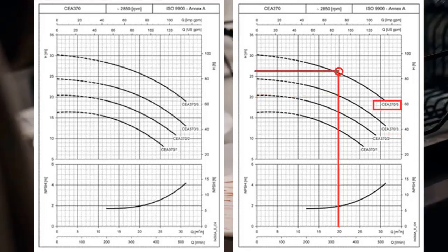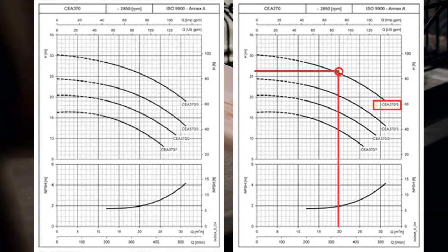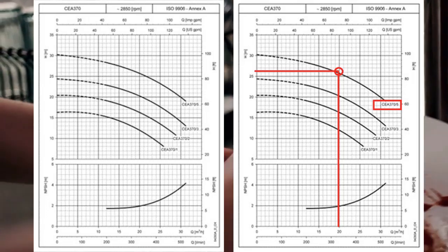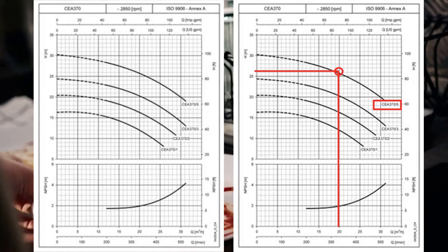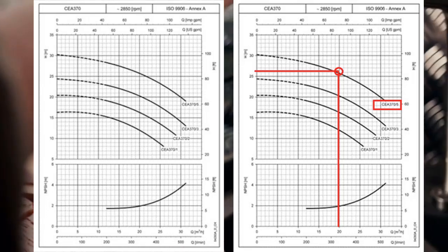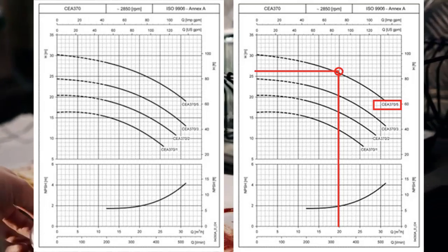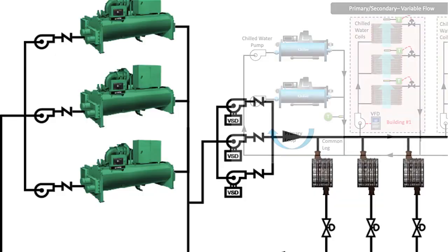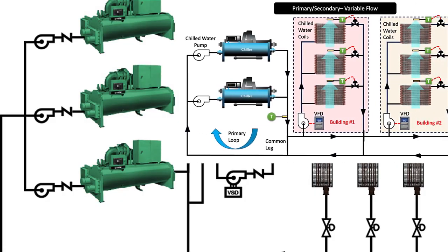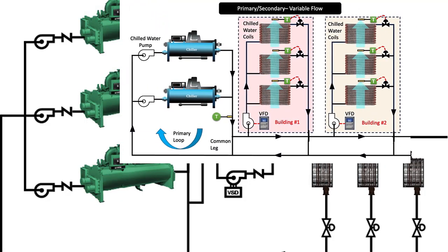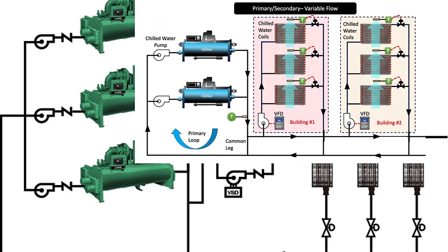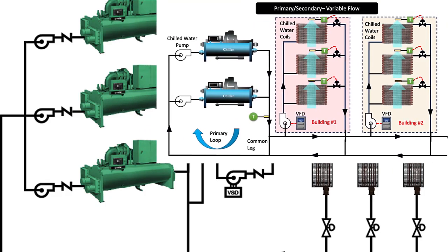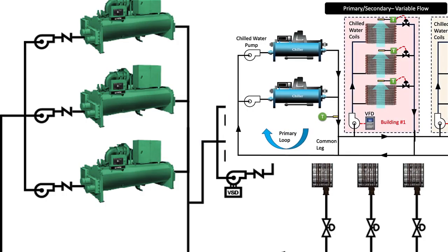If the pump is to be located external to the chiller, and the chiller has a 0.5 bar pressure drop on top of the 2 bar pressure drop in the circuit, you will need a pump that will deliver the flow rate of 20 m³/h at 2.5 bar. Of course, the system design may have a primary loop and a secondary loop, but you still use the above for each circuit, with the exception that the flow will be divided up amongst the various circuits.